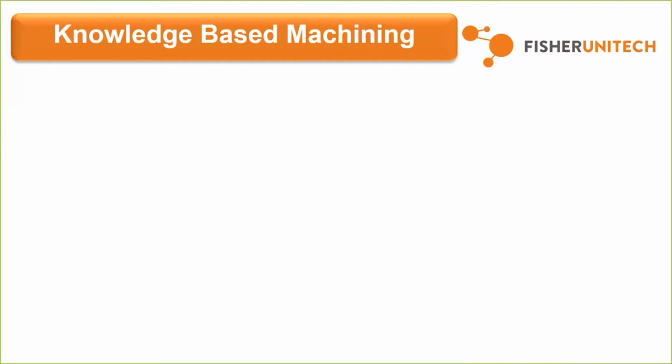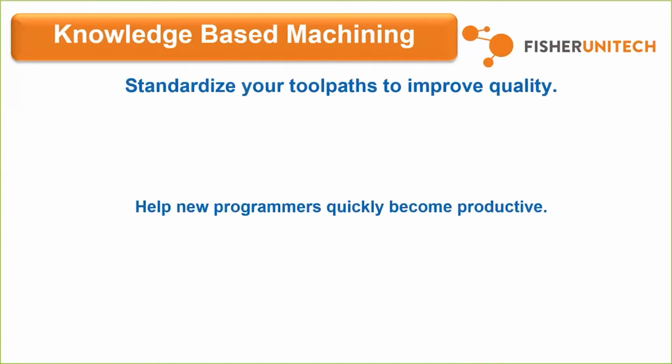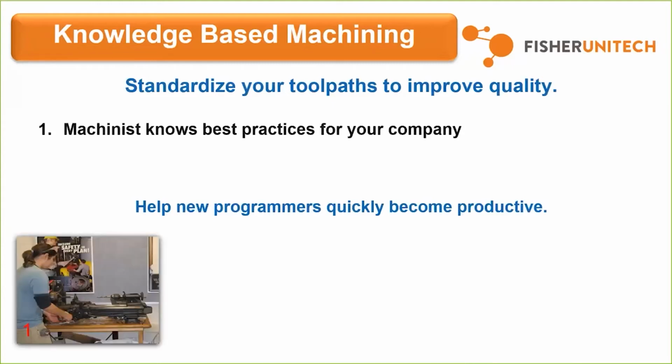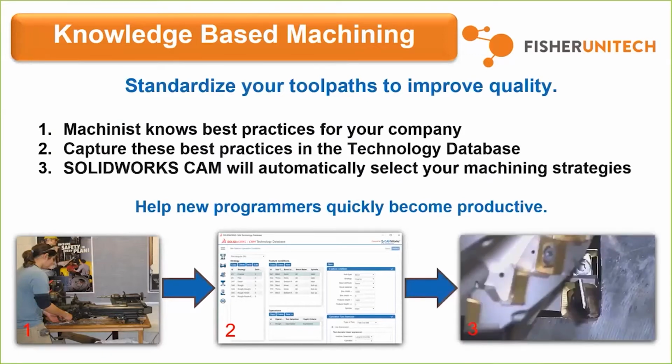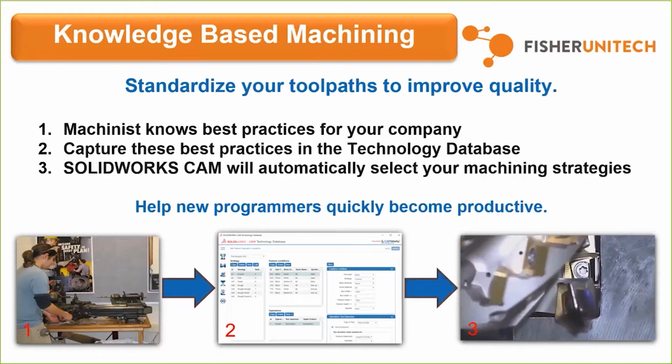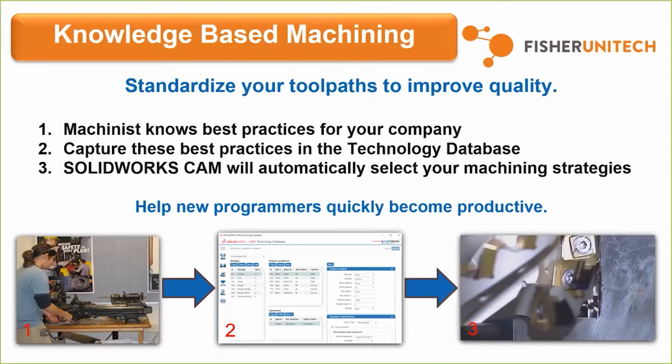You also get what's called knowledge-based machining. So with SOLIDWORKS CAM, you can actually standardize your toolpaths to improve quality, and you can also help new programmers become quickly productive. The way that we do that, basically the process here, is that your machinist knows the best practices for your company, right? And then they can capture those best practices and save them to the technology database. And then they can be referenced later when you choose automatic feature recognition, and SOLIDWORKS CAM will automatically select those machining strategies.